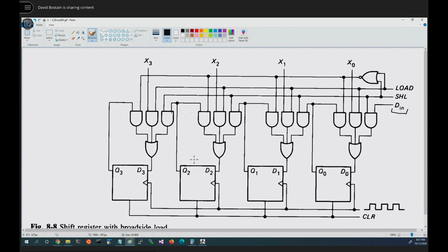You can imagine this being useful to restore the value. You've got an assembly line. In the middle of using the assembly line, you've been keeping track of where all the parts are with sensors and mostly in the software through whatever value is stored in these flip-flops. During the day, you lose power. You restore power. The flip-flops are all clear. We don't know where the parts are anymore. Yes, we do. These sensors know exactly where they are. So we shift them through into the flip-flops before we start using them, so we'll do the right thing to the parts that are on the line already. And there's many other uses where you might want to do that.